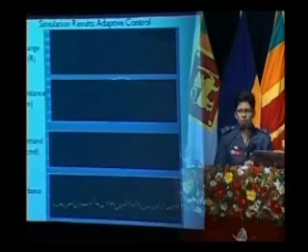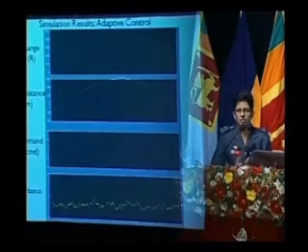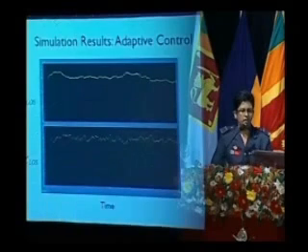This is when the adaptive control part came into play, where I gave a disturbance. This disturbance is just a random disturbance, which can represent aerodynamic loads or gust wind forces or any other external disturbance that the interceptor may face during its flight. Depending on the disturbance, the command input will also change in order to get the desired system dynamics. And again, the change in the line of sight angle remains more or less around 0, with slight disturbances due to the wind forces.